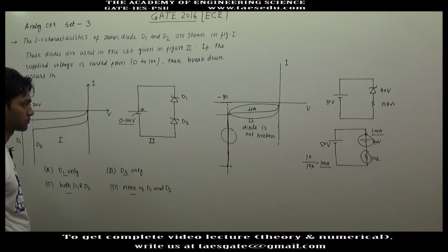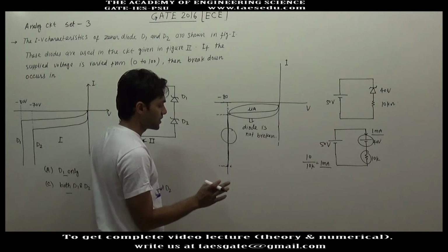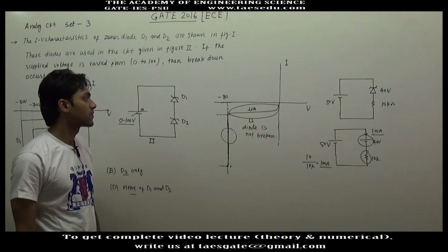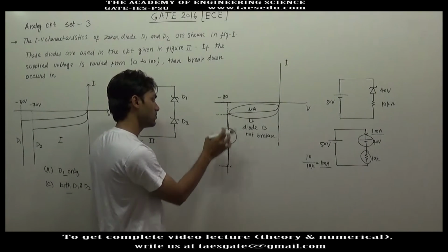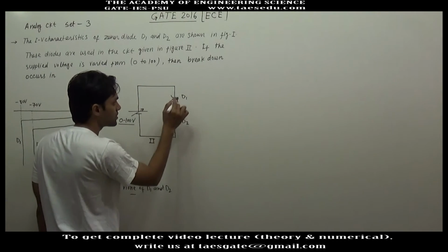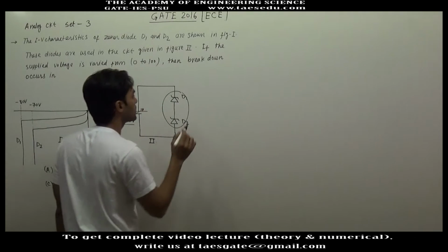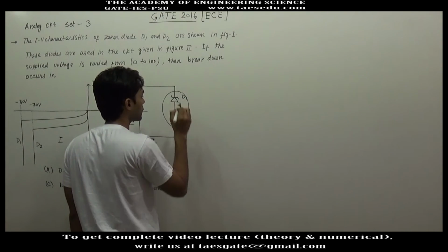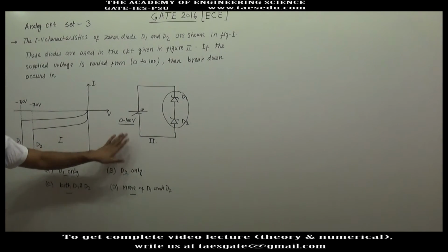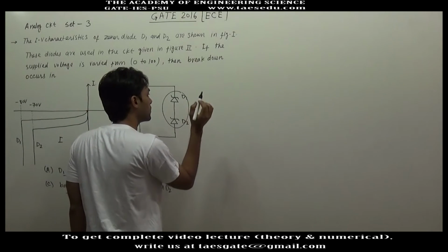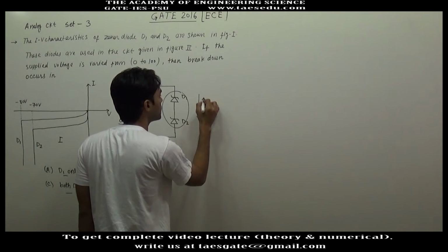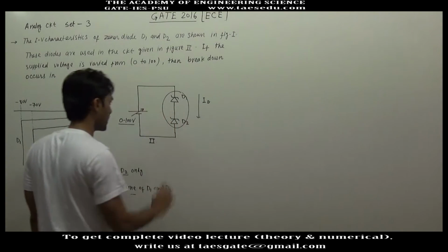Okay. So my purpose is to explain to you that the meaning of this line is not that the current will be very high. It means that current may take any value between these values. The other thing is that the two switches are connected in series. So it is very clear that the current through them, it doesn't matter which diode or both of them are broken, it doesn't matter. In each case, current through both the diodes will be the same. Okay, ID will be the same.